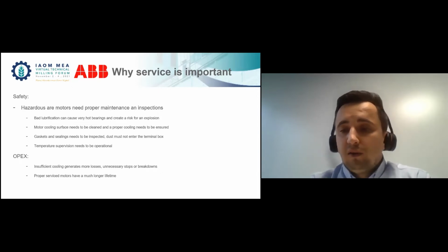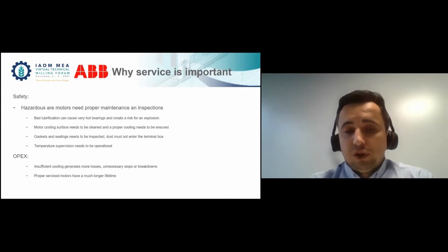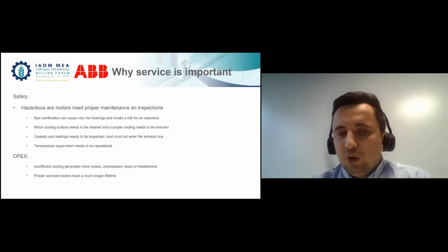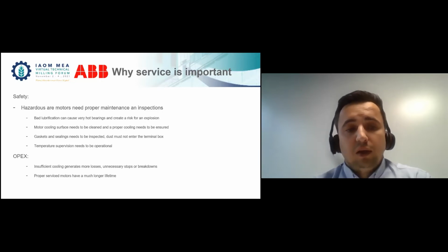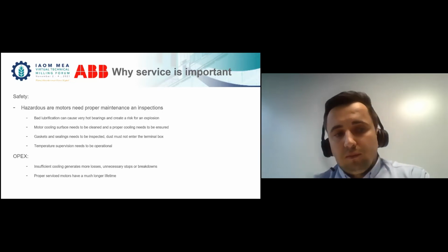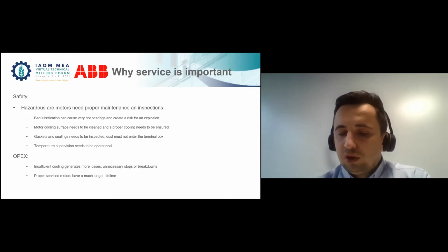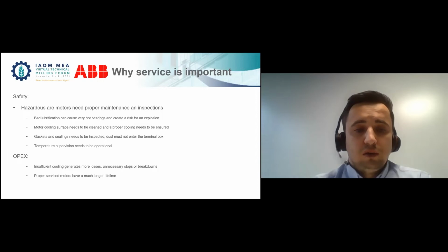So the maintenance, in addition to normal application motors, is much more important for hazardous area motors to ensure safe and reliable operation. As we know, there are costs as well: insufficient cooling generates more losses, unnecessary stops or breakdowns. Bad lubrication creates motor failures, and also production loss. So those topics need to be considered very well to ensure optimized production and output of your factories.